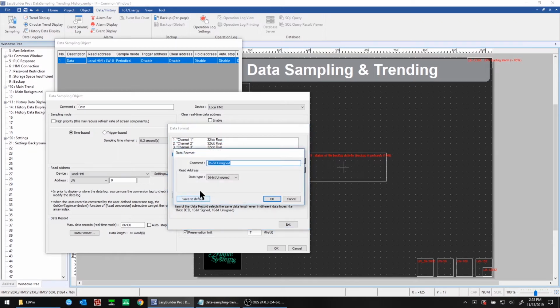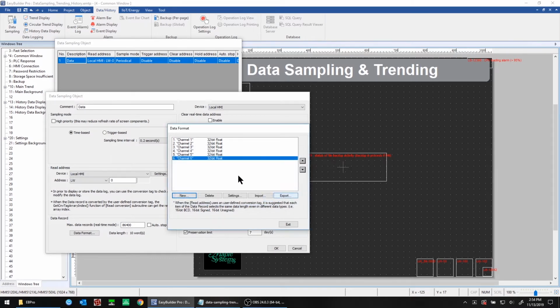If you wanted to create a new channel representing a different value or variable, you can do this by clicking on New and then giving it a name. For instance, channel 6, we could add and then set it to 32-bit float as well, or some other data type if we wish. Click OK to add that. Now we would have 6 data points we'd be reading in every 0.2 seconds in this case. Now we'll delete this one because in this example we just need 5 channels, but that's how you would set up your data records in the data format section.